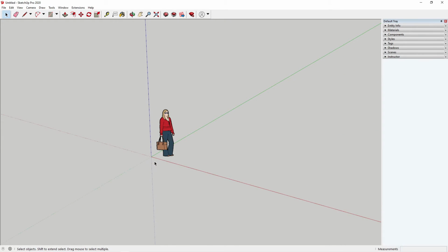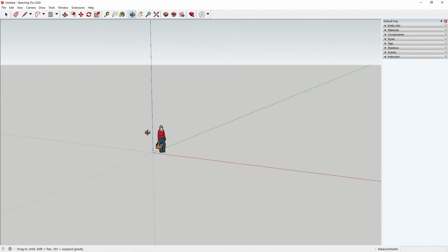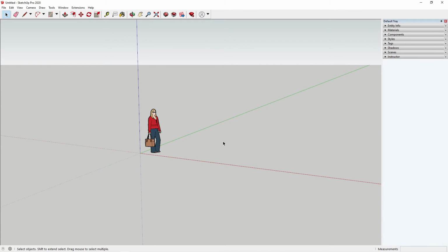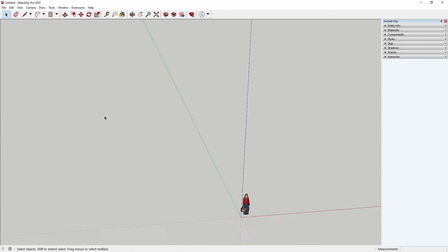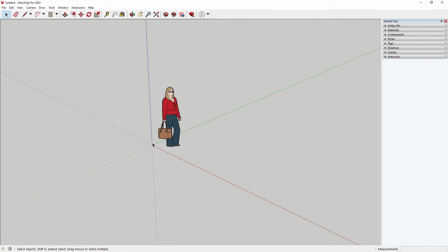The first thing is, if you notice, we can see some lines, a vertical line and some horizontal. What's the usefulness of these lines? These are axes. These axes give us a sense of space. This axis helps us to know when your line is vertical, because it snaps it. For instance, let me just draw a line, and you see SketchUp automatically snaps your line towards a perpendicular axis.